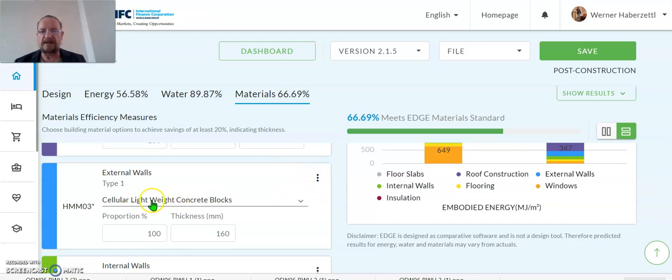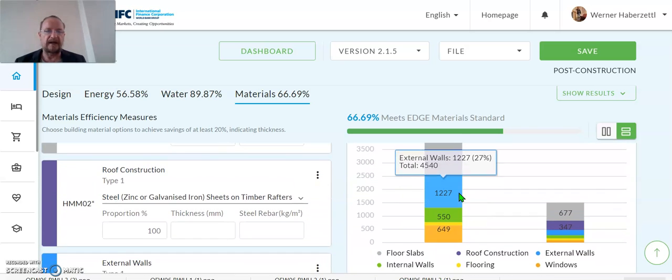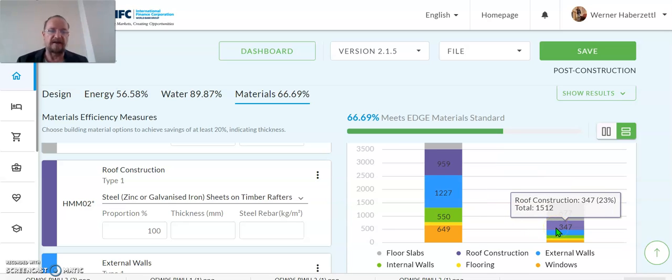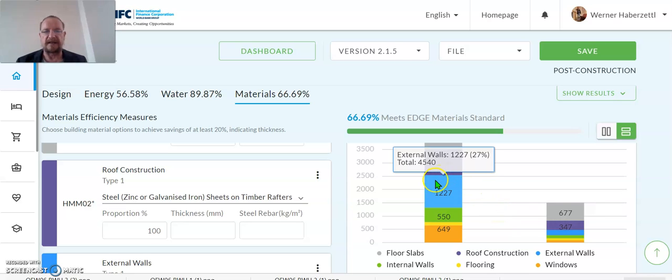So why did we actually get such a high saving? How could we save so much energy, embodied energy, between the baseline and the technology, the hollow blocks which we used there? That is actually quite easy. In the Philippines, they're using also hollow blocks, but they fill the hollow blocks in with mortar. So in the construction, they use the hollow blocks and fill them with mortar. And of course, the insulation value and of course the embodied energy is in this case much higher.